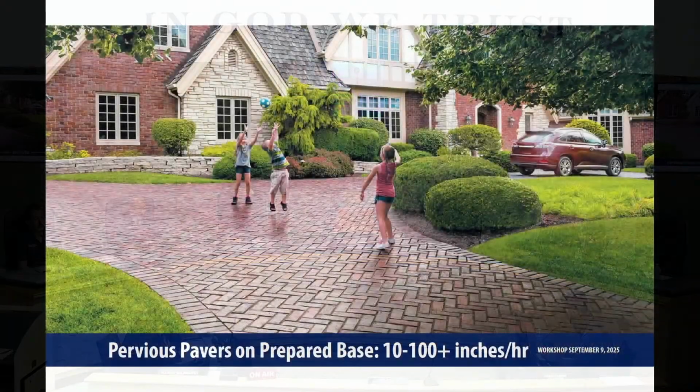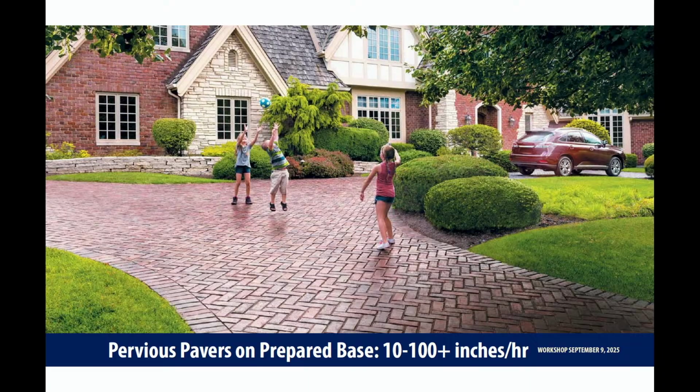On the pavers, you showed several pictures of pavers. That one right there, that's your standard paver? That's a pervious paver. It's a Unilock product that they manufacture. It comes in many styles, but the voids are large enough and they specify a detail for the base layer. It's probably 8 inches or some thickness. The voids are what's pervious. So the paver itself is not pervious, but the way it's installed with the subgrade and the voids in between, that's what makes it pervious.